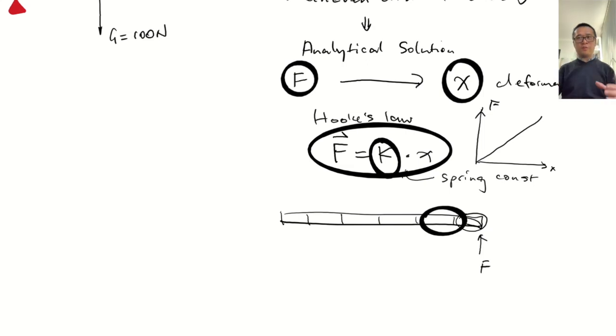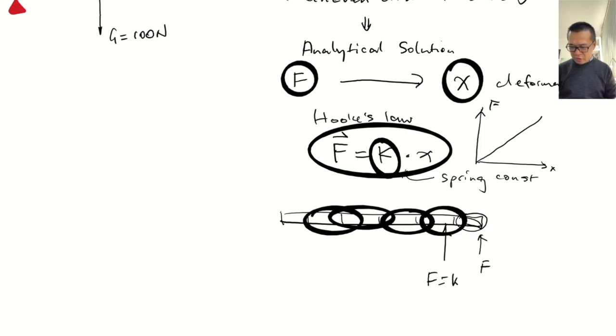I know the whole bar is going to deform non-linearly with a complicated shape, so Hooke's law doesn't hold. But if I divide it into smaller elements, I can actually apply Hooke's law in each individual part and solve the deformation in the whole body. In this way, I can understand how complex mechanical structures behave in real life.